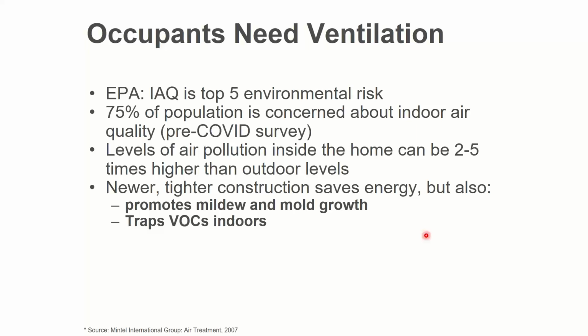Residentially, if you look at any of our energy codes, there is leakage requirements for how tight the building needs to be. And because of that, they're doing blower door tests to make sure the building's not leaky. Because of that, residential buildings now require mechanical ventilation. Commercial buildings have required mechanical ventilation for decades, so we were already there on that part of the equation.